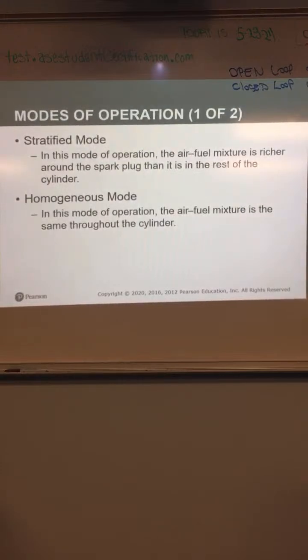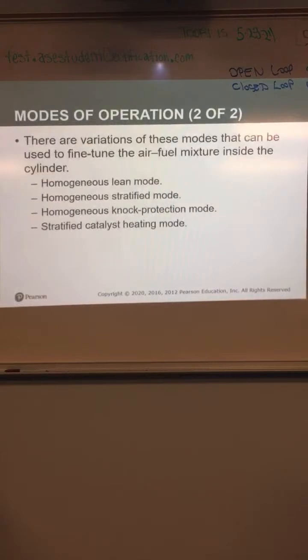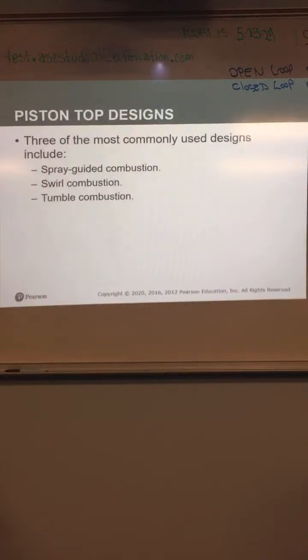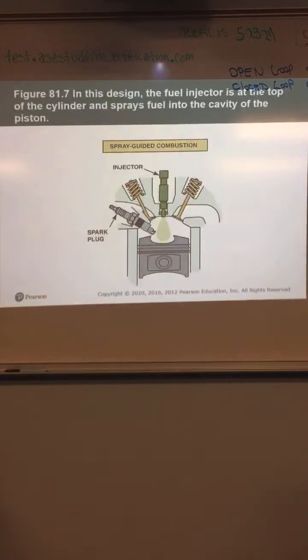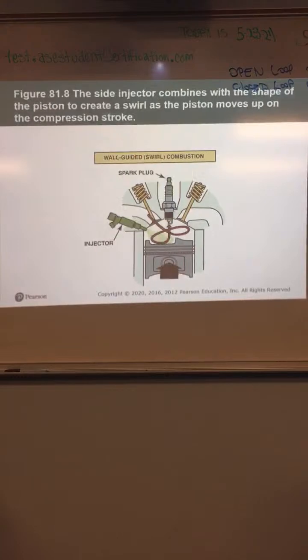Different modes, I believe there's 3 different ones: stratified, homogeneous, and maybe that's it. Oh, stratified catalyst heating mode, knock protection. These can be used to fine-tune the air-fuel mixture in the cylinder. Piston top designs, depending on where the injector is located, it's gonna have a different type of piston top, where you got it, swirl, combustion or tumble. Do we need to know the modes of operation? Probably not, no. Okay.